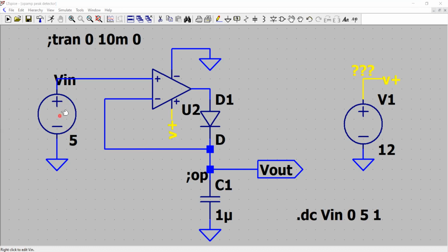So let's say I have a positive voltage applied of 5 volts. Apparently, the voltage at the positive input is greater than the voltage at the negative input. Hence, the output tends to be positive, and if that output is greater than the forward voltage drop of a diode, it makes the diode forward biased. Then the loop gets completed. This signal comes back to the negative input, and then the circuit is apparently a voltage follower,